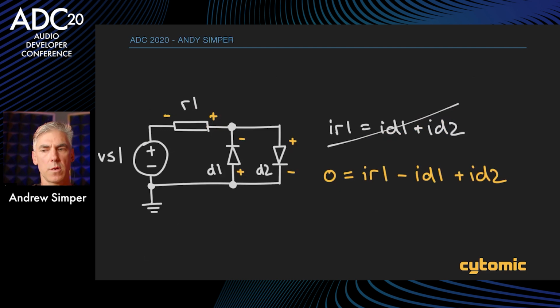I cheated a little bit on that last one, because it's not actually just the addition of these. These have a direction. One points up, one points down. It's pretty clear; there's an arrow in that symbol for a reason. What happens is that these diodes clip the voltage coming in. They take the top and bottom off a bit, and that is the equation. There's a little plus and minus to show you the direction.